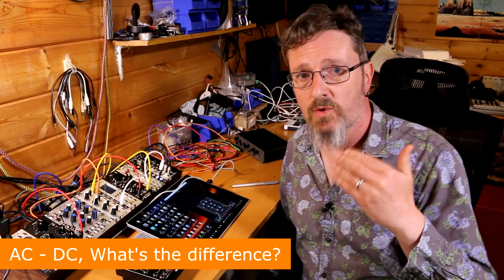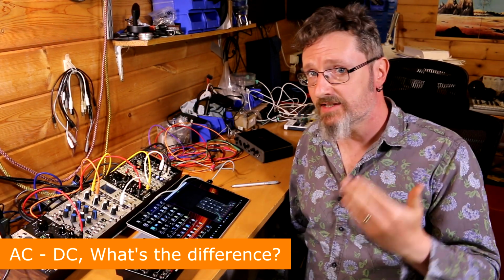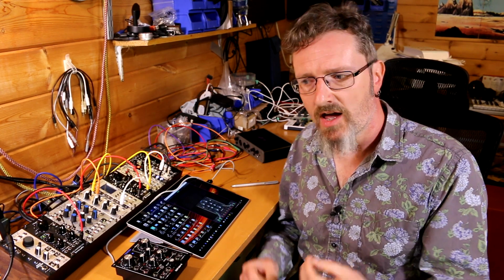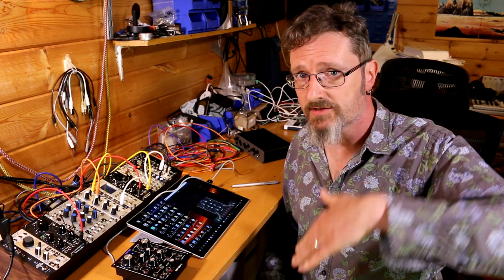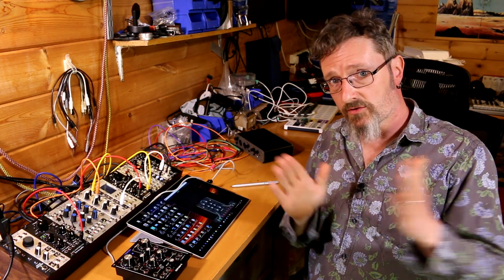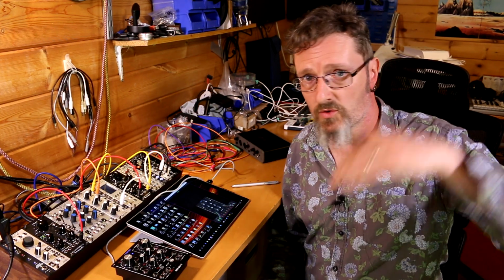So why is there a difference? Why do we have AC coupled audio interfaces and DC coupled audio interfaces? Well, very simply because it's to do with what your audio interface is trying to achieve. I mean, normally speaking, you just want audio signals, and so a manufacturer will design their interface to exclude or filter out anything which isn't an audio signal.